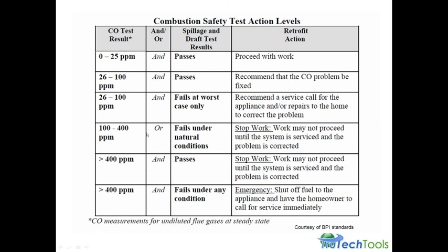So 0 to 25 ppm, and it passes the spillage and draft test. And we're going to talk about that in a few minutes. You can proceed with your work. 26 to 100, and it passes the spillage test. We're going to recommend that the CO problem be fixed.